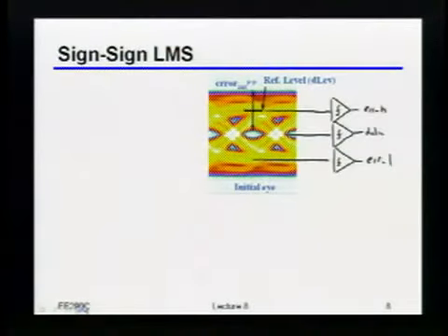Okay, so it turns out there's even a name for this. It's called sign LMS. Let's say I'm really lazy, and I don't even want to deal with the analog value of the input to the equalizer. So the only thing I'm going to deal with is the sign of the analog input and the sign of the errors. Okay? So it turns out, by the way, this is called sign LMS only because normal LMS is called just normal LMS, meaning everything is analog.